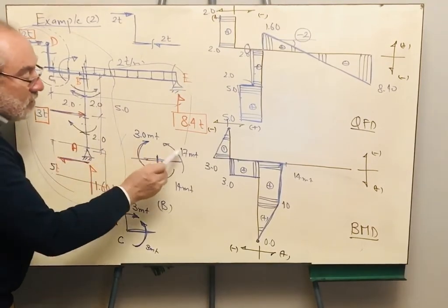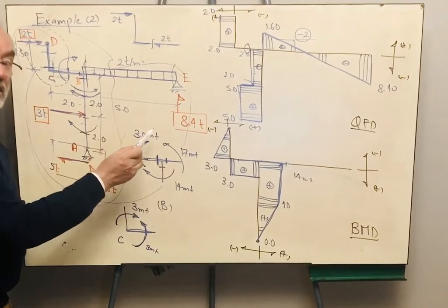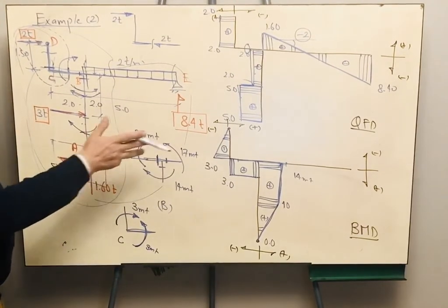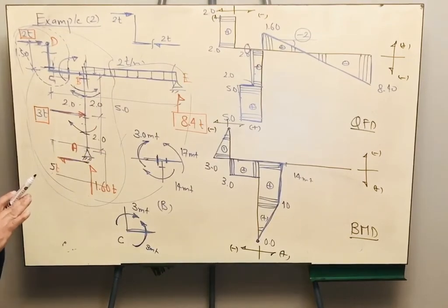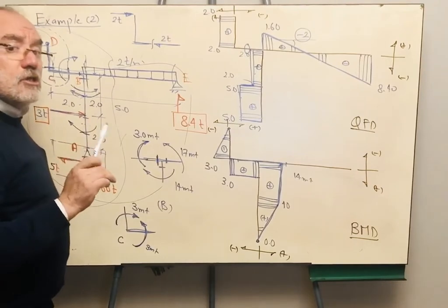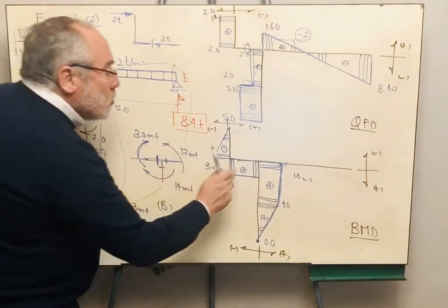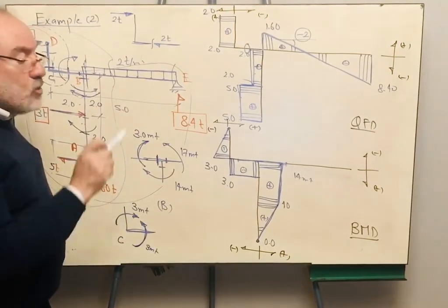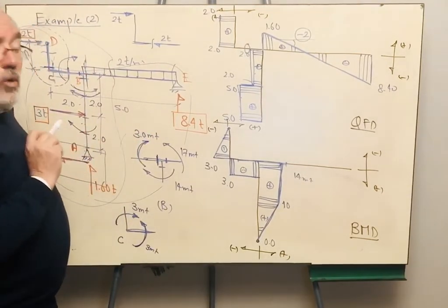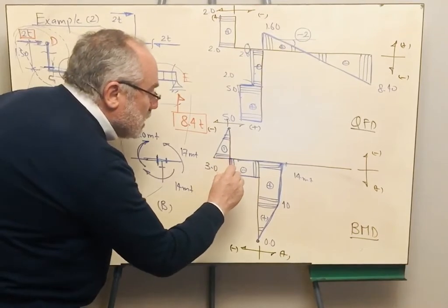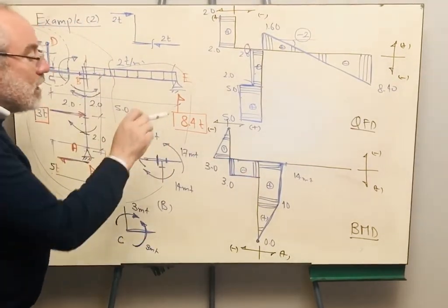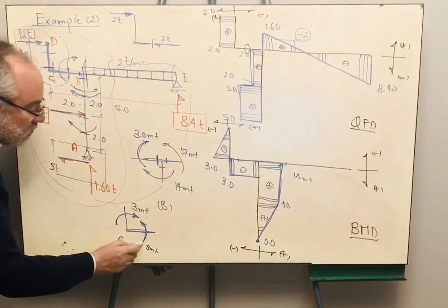Whenever you are getting these values, you have to balance the moment at point B. Then we go to the classification of where we should draw the bending moment itself. Take care. If one of the students by mistake wrote this one as negative, I will still give him or her the full mark. Why? Because he or she drew the bending moment on the correct side. It is drawn below the datum at the side of the tail of the arrow.